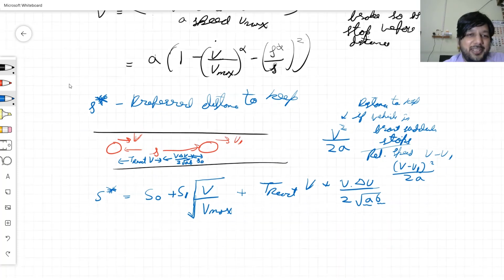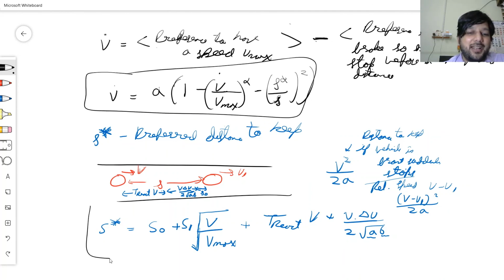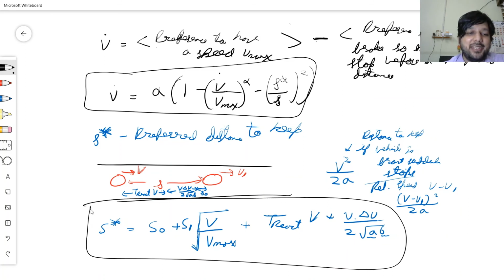So how the simulation really goes along is that now I just need a linear speed, and therefore I need just one control law, which is this one, and this is the equation that I use to get my preferred distance, which goes over here. So there's just a linear speed that I need to control. That's how I'll manage my acceleration and brake, that's how I'll simulate the vehicle. And the good thing is that there are a lot of primitives from the fundamental diagrams that we have already incorporated into this as an equation.